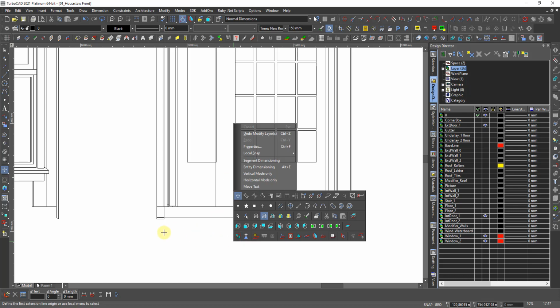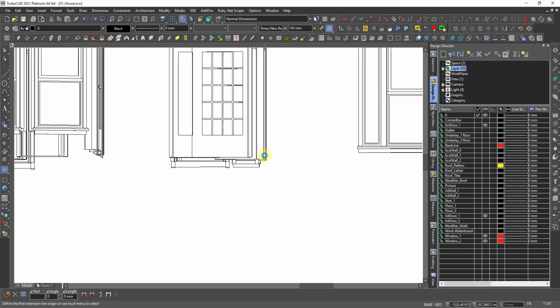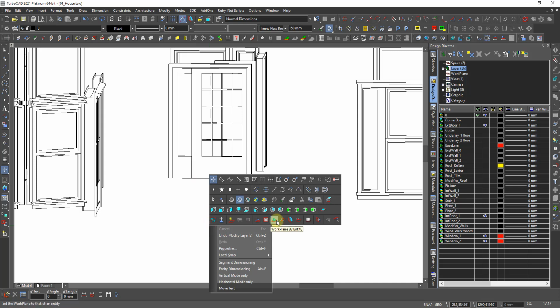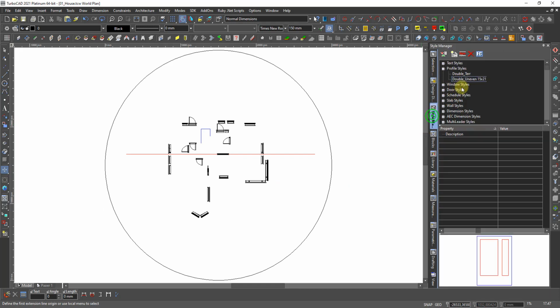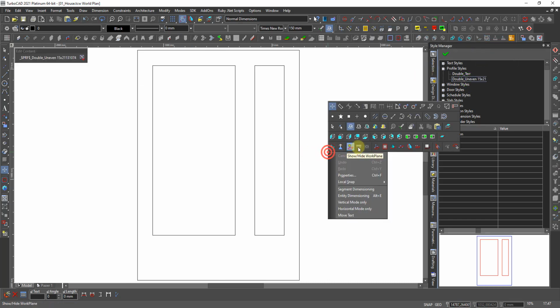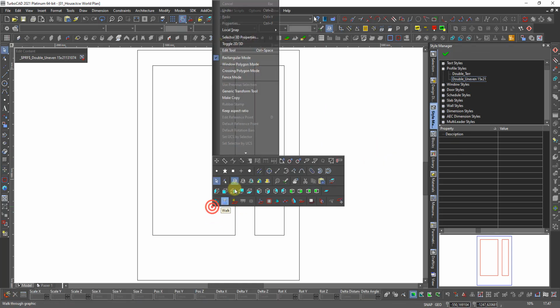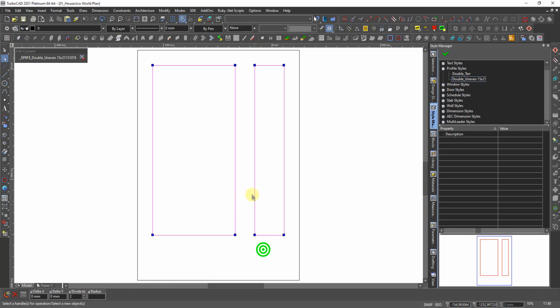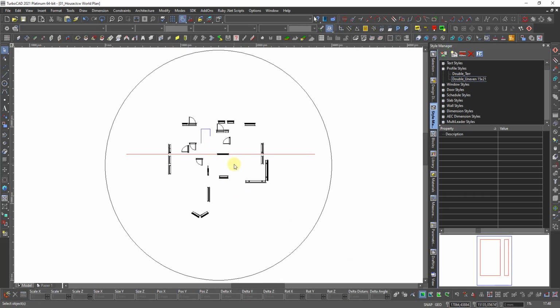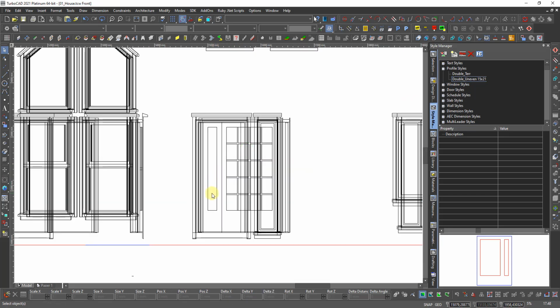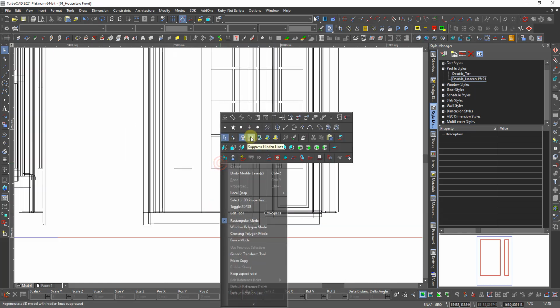Then I go to, why is this up there? I go to wireframe, I go to top, I go to style, I go to this, edit content. I'm sure I'm on world, and I do edit. I say this two should go 10 centimeters this way. That is positive X, 100. And that should be OK. And edit this. And I can go to front view. This looks similar to me, yeah. And I go hidden line, and now it's correct.